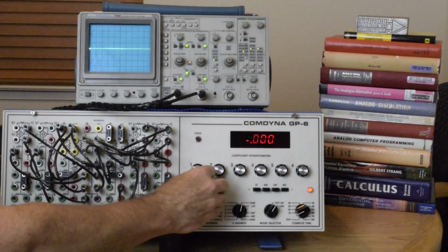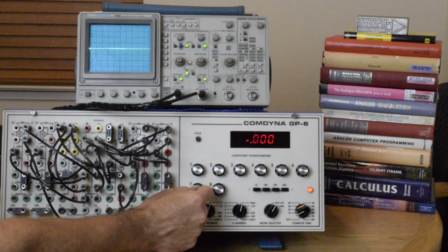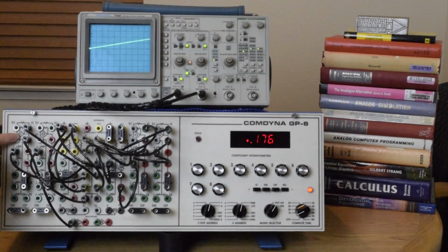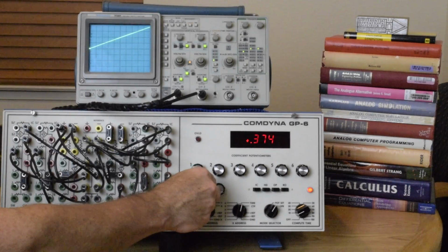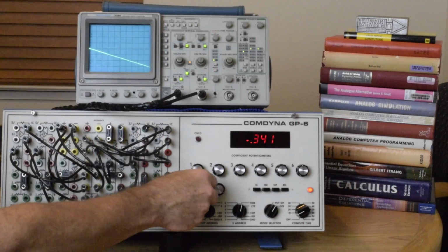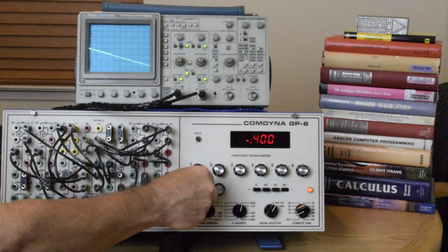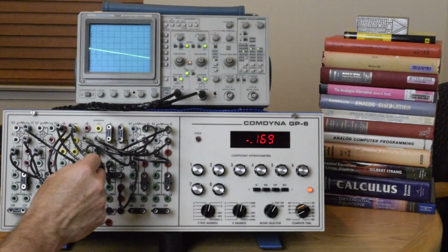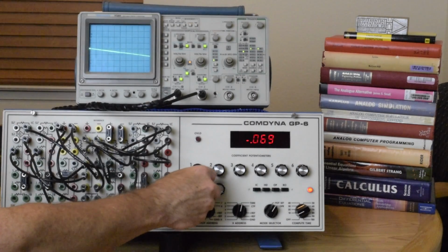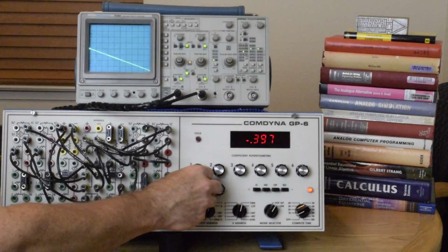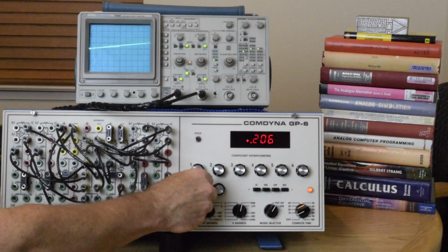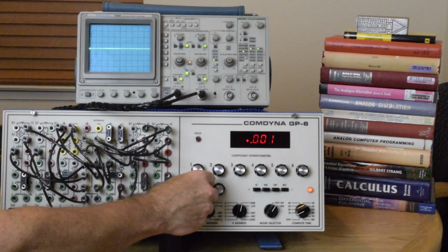So now we can actually introduce a slope of m here with potentiometer 7, that's on the very input of the integrator, and we can adjust the slope of the line. And because I set this problem up using the two-ended potentiometers, we can actually apply a negative slope as well as a positive slope. And then this is where we were in the beginning with 0.